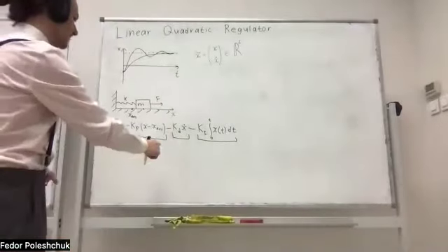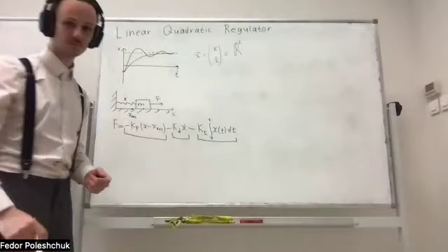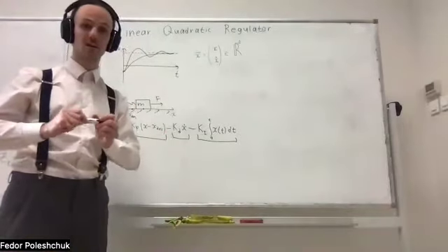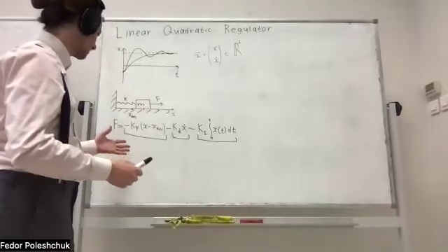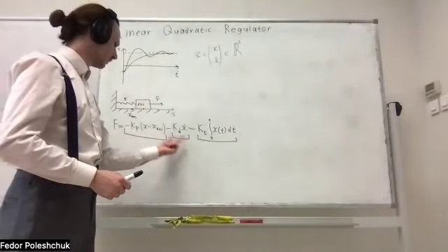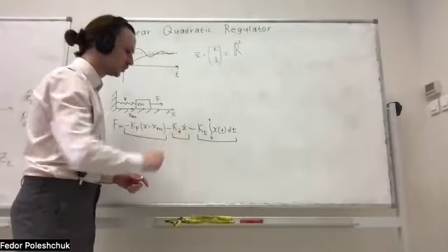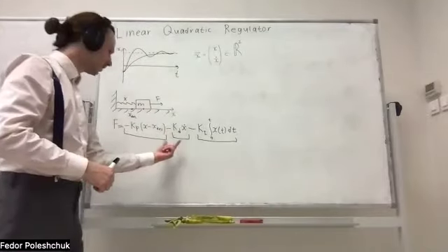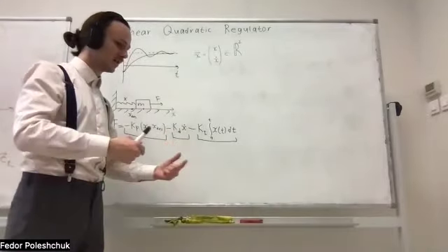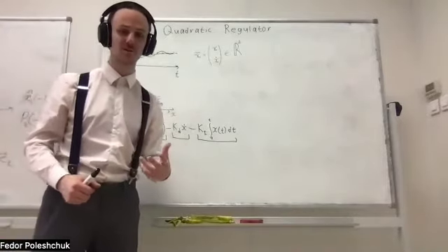And the second is called derivative because it's proportional to the derivative of the coordinate. It's proportional to the speed. Why does it really make sense to do that? Well, it turns out that with this term, we are counteracting the velocity. So if the velocity is very high, with this term, we will act upon the block in the other direction so that the velocity will decrease.